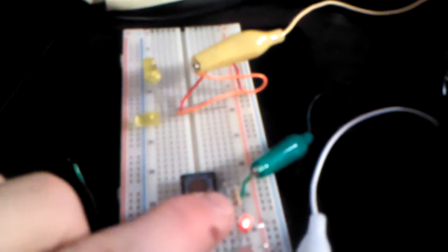What's interesting about these four-legged buttons is that these two pins are connected and these two pins are connected. So you have to hook a resistor to the ground and the pin, it doesn't matter which side, but the resistor's hooked to the ground and the pin's hooked to pin 25. And so when I push the button, it connects this pin with this pin, the signal with the ground, which then tells the code that the button is false. That's turning on the LED.